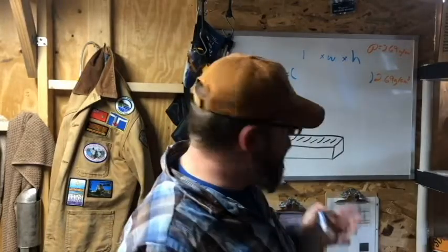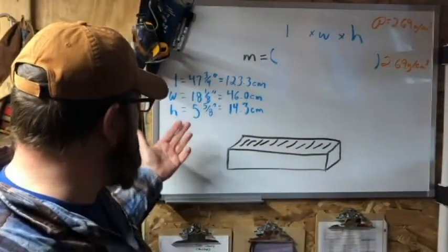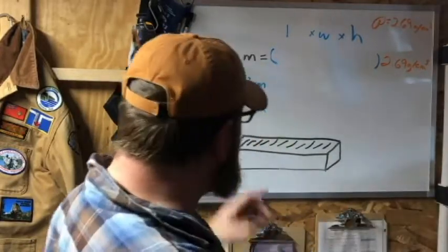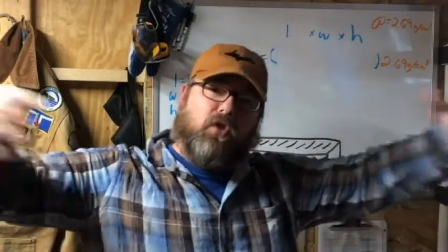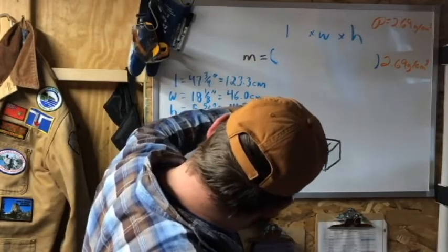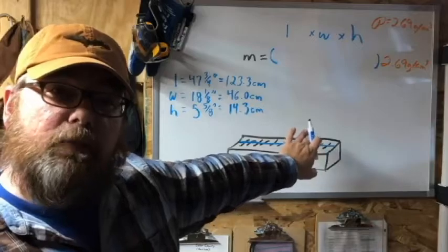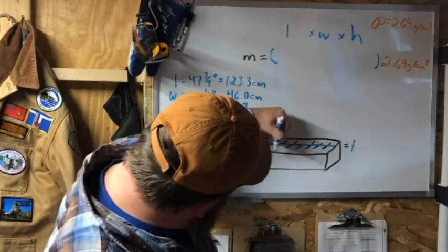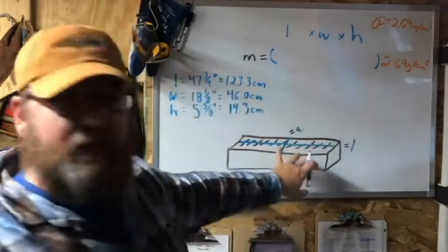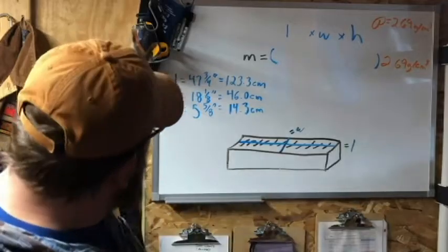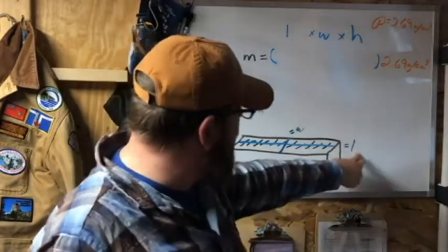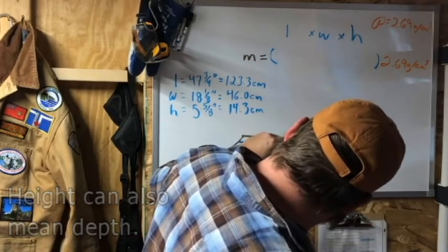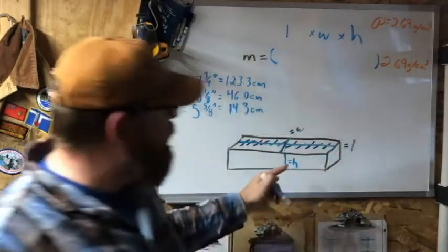But where do I get my length, width, and height? Well, I did it at the beginning of this video. We took length, width, and height measurements with an actual ruler. And which way is length, width, and height is kind of arbitrary. In this case, and in most cases, your length will be referred to as your longest part of an object. And in that case, that was this. This was our length. Now your width is going to be 90 degrees to that along the same plane. So that was my length. My width is right here. That equals my width. Now remember, this is a 3-dimensional object represented as 2, okay? And my height is generally taken as what would be our z-axis. This would be our x-axis, this would be our y-axis, and this would be our z, but we have a specific height there, so we can just extrapolate it, and this is equal to our height.